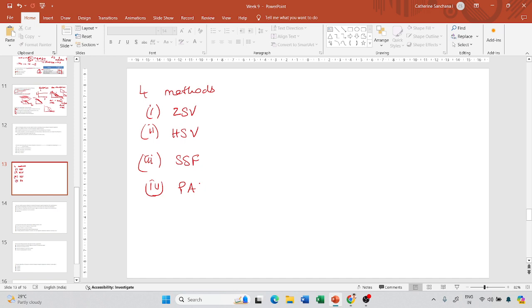Okay, so these two are determined using a rotational viscometer, which means it is a cuvette arrangement. What is a cuvette arrangement? It will have a cup and a bob spindle. Okay, so this is stationary and this is rotary.